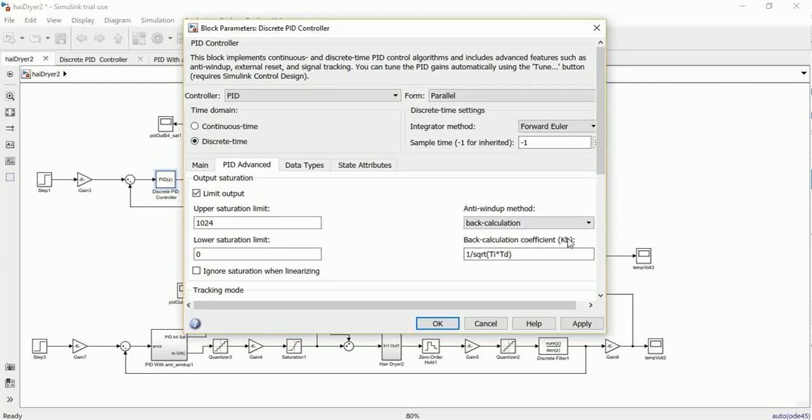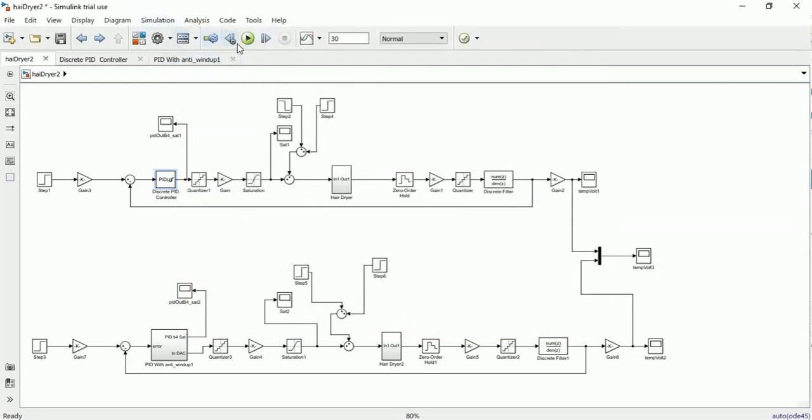So we are saying that this time constant is between Ti and Td, and that's why the bigger Kb, in theory, the better, the faster we desaturate the integrator, because the shorter this time constant will be.